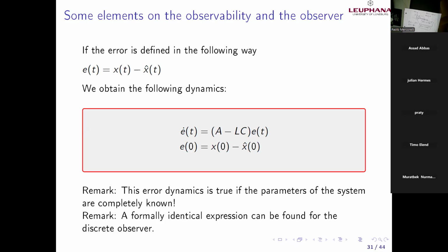If it's not stable and the system characterized by the eigenvalues of A is stable, or better to say asymptotically stable, we cannot observe, because the dynamics of the error go to infinity. But very important, we will see a little bit better concretely with the example, the eigenvalues of the observer must be larger in absolute value. Again, absolute value, I emphasize this concept here because of the stability or asymptotic stability. I will clarify a little bit better with this MATLAB simulation.